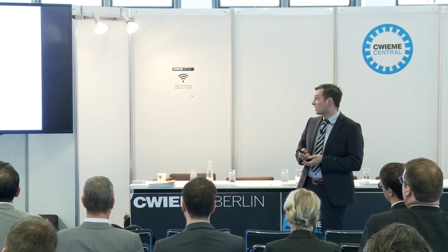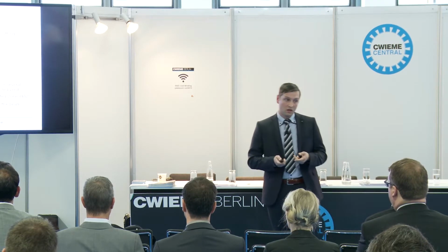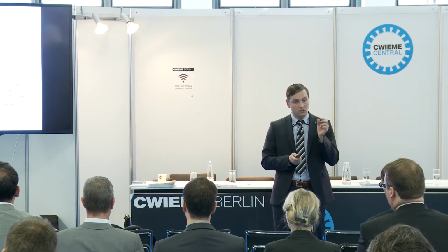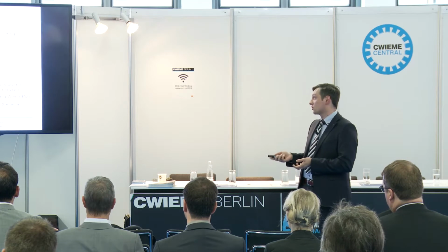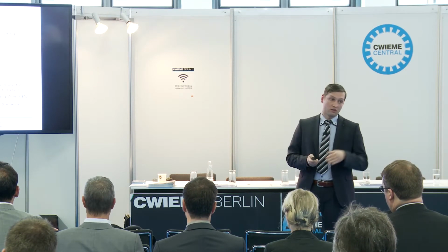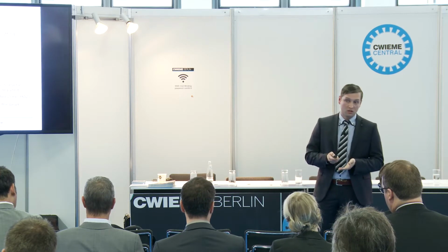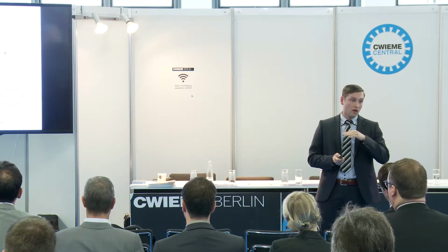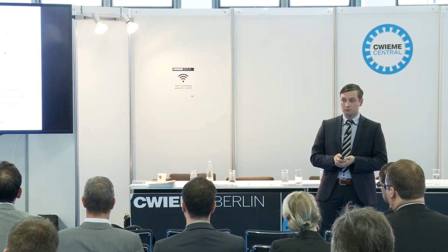And so the cutting is done in several cycles. Due to this gradual ablation, we just see a very small heat-affected zone. And unfortunately, there is some burr left on the top side of the layer. But with an additional burr removal, it's possible to remove that burr and to modify the shape of the cutting edge.